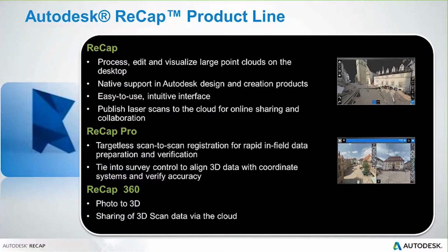Recap Pro allows us to do targetless scan-to-scan registration. So rapid field data preparation, a lot of customers that are using our targetless registration are doing their registration in the field. This is a big shift in the way that we do scanning, and there are workflows that can be very effective. Also tying that survey data, the scan data, into survey control.